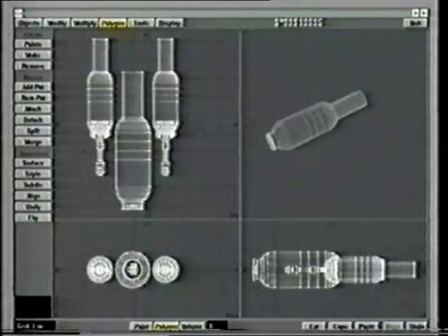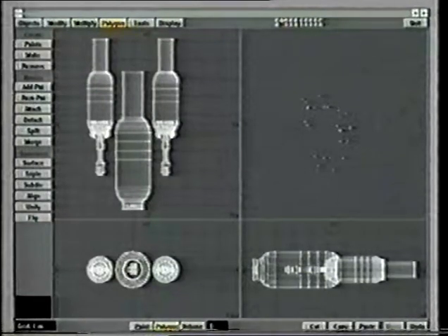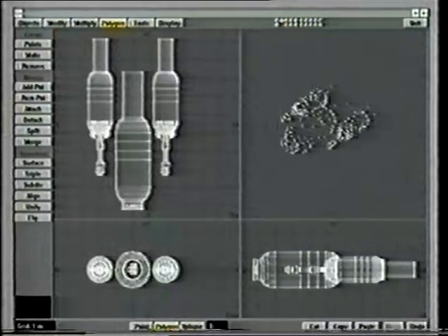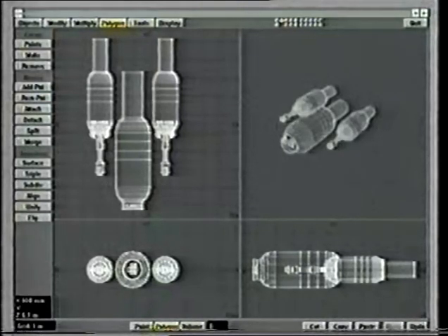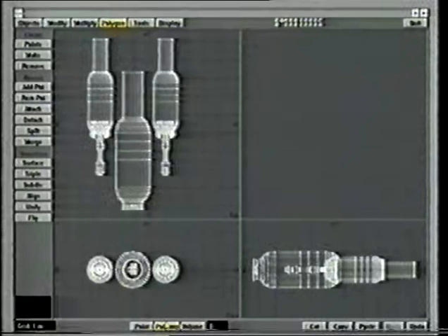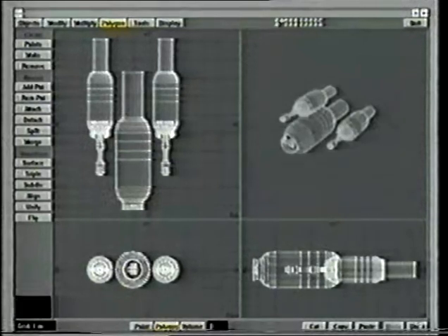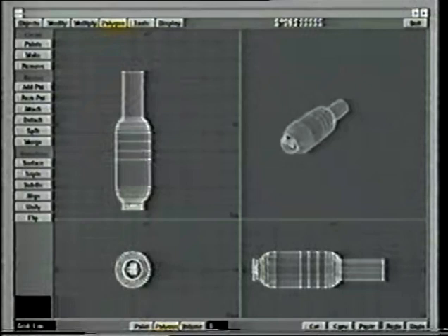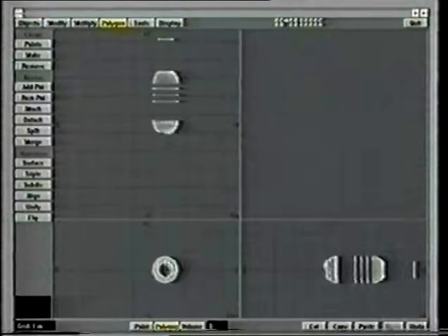Now the thing is starting to sort of show a little bit more of its three-dimensionality, what it's going to be like. So what I want to do is I want to finish off the back part of the main fuselage here and then go on to doing a little bit more detailing. So let's put that in the background layer. In fact, what I'm going to do first, just to make the screen refresh a little bit faster, I'm going to undo the paste there and keep them in another layer.